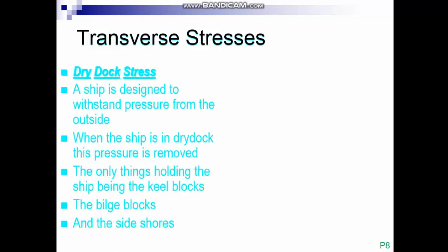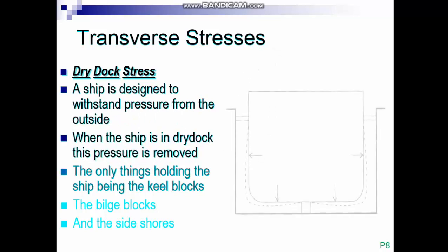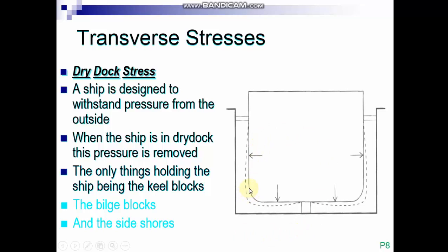So another one is dry dock stress. This is completely opposite. When the ship is on the dry dock, all the water is taken out, and there are only blocks supporting the ship.